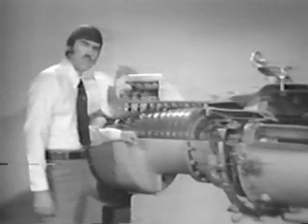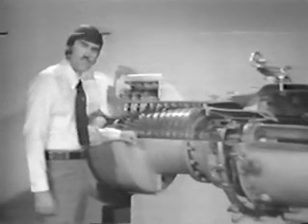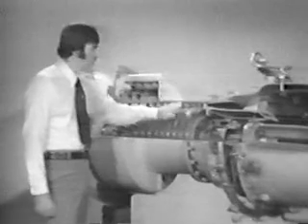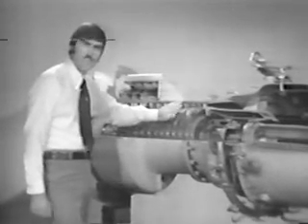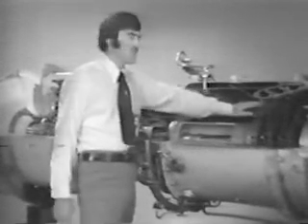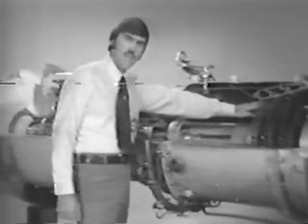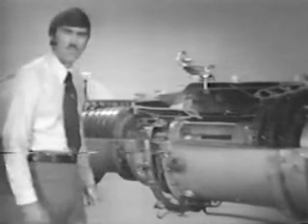In the turbine engine, the unique relationship between pressure and velocity explains many operating principles. In the compressor, the air is slowed and compressed. In the combustor, the air is heated and expanded. In the turbine, the air is speeded up to be used to turn the turbine wheels, and then is exhausted into the atmosphere.